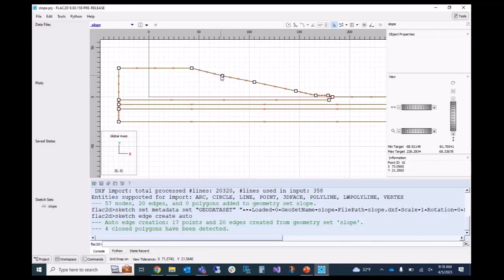So we could either get rid of these points, if we wanted a structured mesh, or what we're actually going to do is just draw lines down from them to make four-sided shapes. And the reason for doing that is we're going to have different density of zoning in different parts of this thing. So breaking it up like that allows us to do fun things like that.